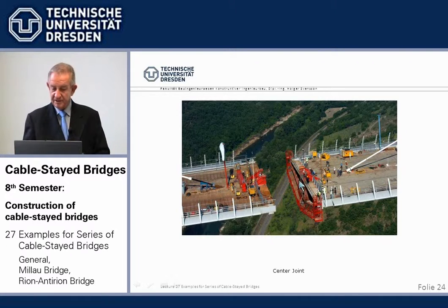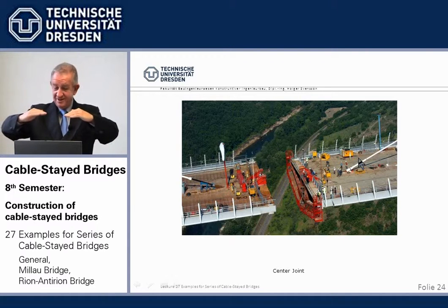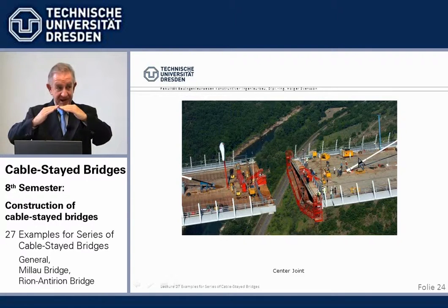We come then close to the closure joint to adjust very carefully. Of course, it helps here immensely to be able, in this case, to pull at the cables. You know, normally, with cantilevers, 170 meters each side, you do not come exactly. You need to be in level, and you have to have the right angle.